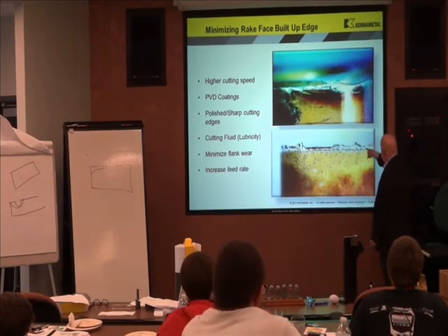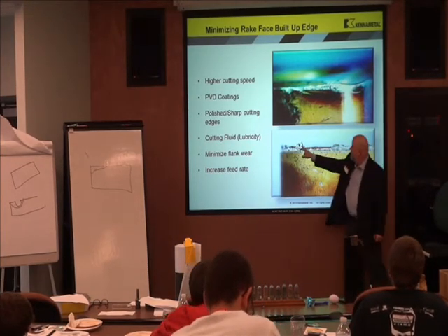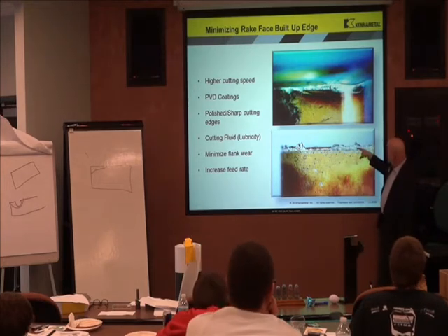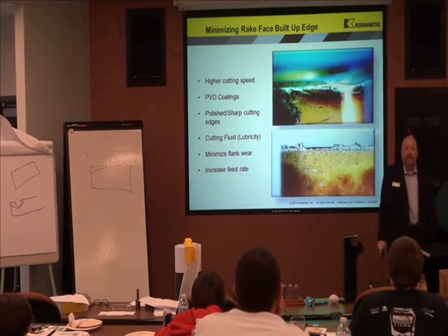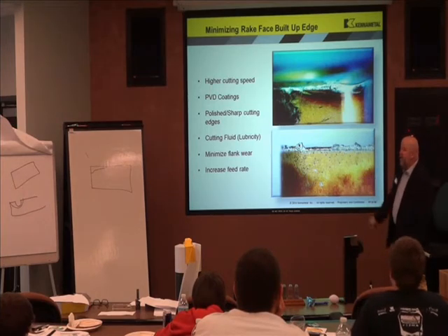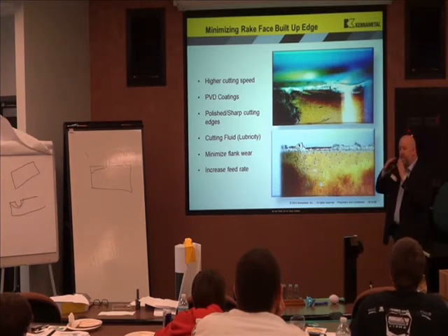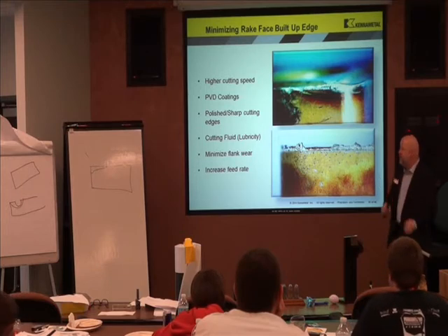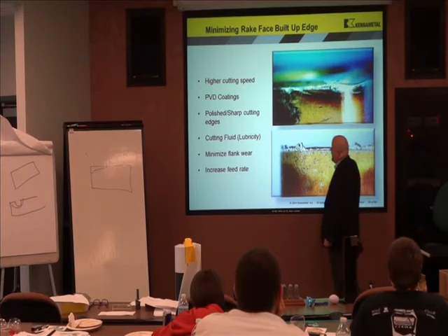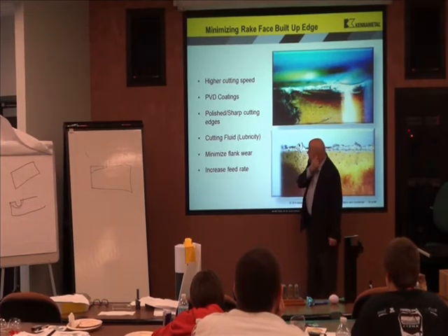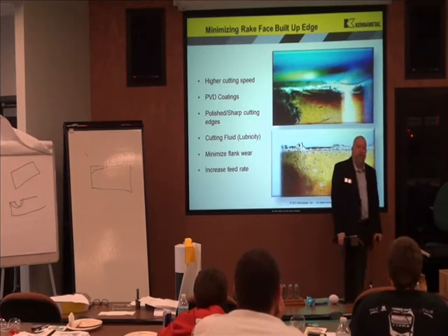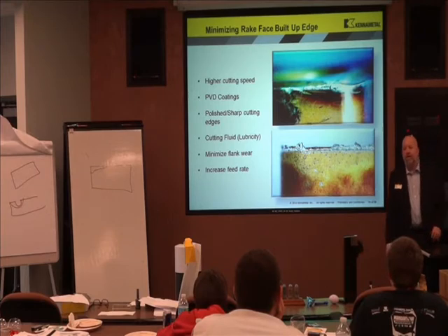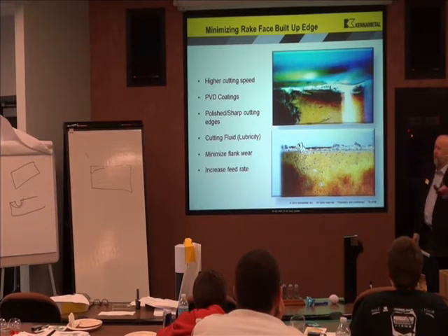That is built up edge on an insert. As it builds up too much, it breaks off, it takes the whole thing. I can use a higher speed. We haven't talked about PVD coatings, but PVD, physical vapor deposition, is usually put on dead sharp edges. I could use cutting fluid. Gives me a little bit more lubricity, but I only like cutting fluid in turning. I do not like using cutting fluids in milling. I will talk about that in a minute.